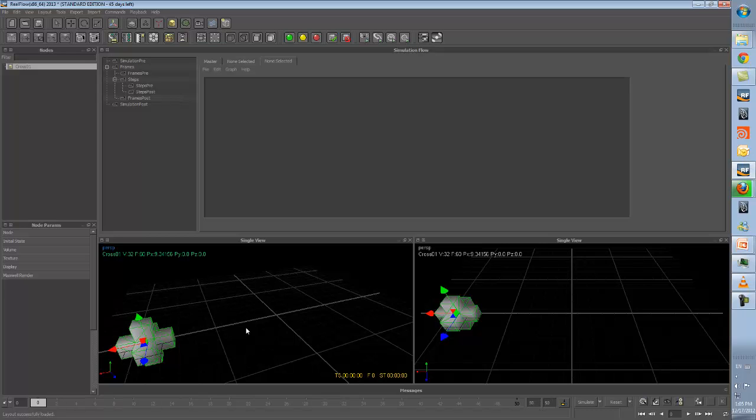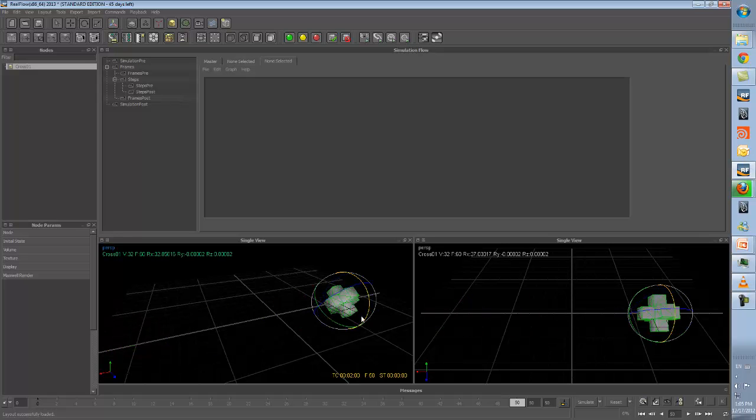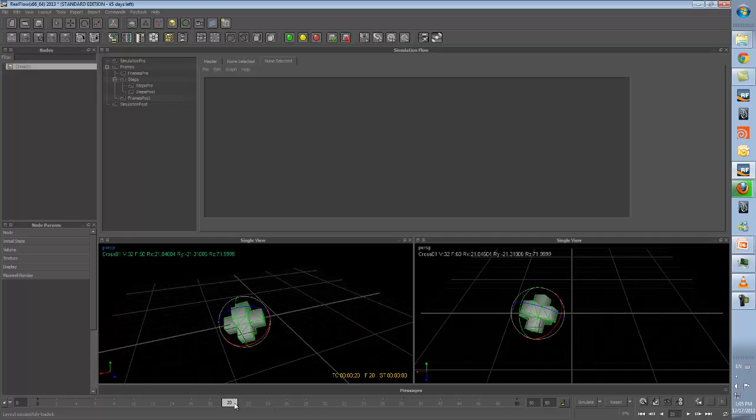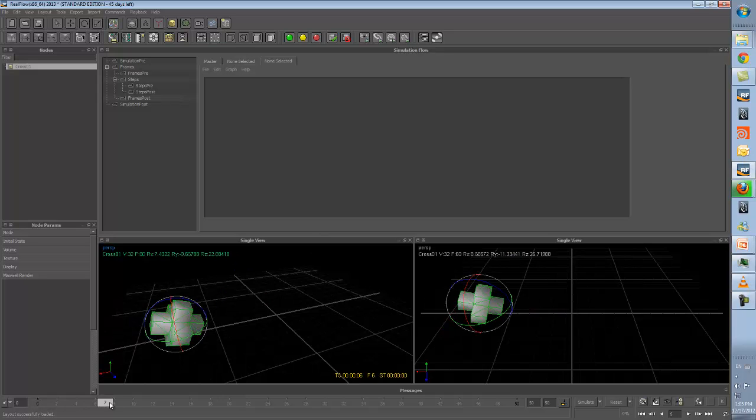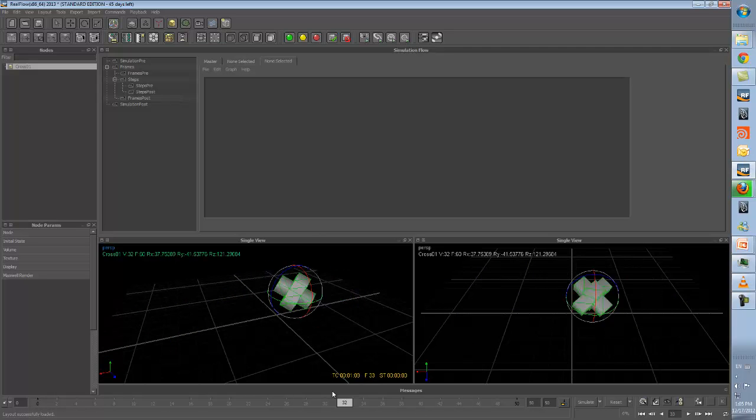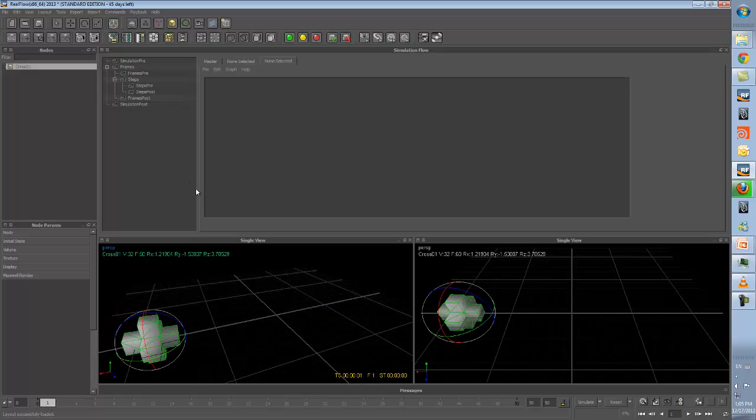Let's play with the frames. Let's say from here you will go to here, and you just do a nice rotation or whatever, and just move it up a bit so it does spin a bit, right? So it is going to be doing that, and while it does that, we want it to be emitting particles from its vertices. If we wanted to do that in previous versions, we would most likely go with scripting, trying to find out the vertices of the object, querying the velocities, and outputting particles from there.